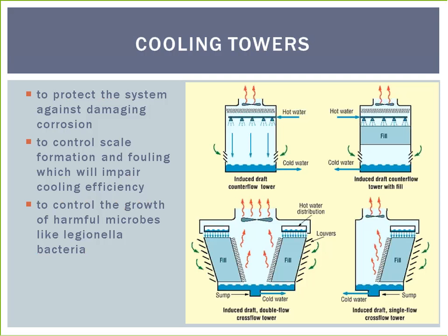It is also important to control the microbial activity and physical fouling, since both can be a cause of severe localized corrosion. Once these basics have been dealt with, you need a good corrosion inhibitor which is matched to the cooling water chemistry and system metallurgy, and to control its dosage effectively.